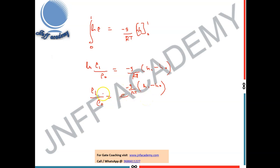So rho 1 is your density variation in the stratosphere. Rho naught is nothing but your known reference value. It could be sea level or whatever it is, or maybe the base of the stratosphere, which is your tropopause. So it is clearly telling that the density is varying exponentially, but since there is a negative sign here, it is decreasing exponentially. It is not increasing. So this is the expression at which the density is varying in the stratosphere.